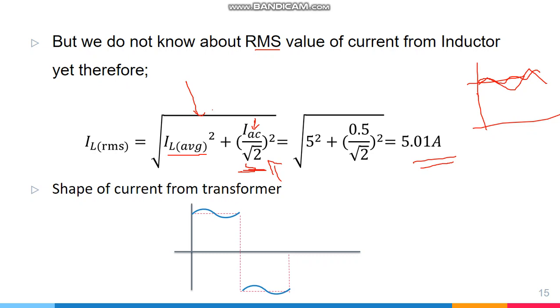You need to understand that this AC ripple is dependent upon the value of the second harmonic voltage V2H and 2 omega L. In our case the inductance was very high, 2.15 Henry, but in cases when this inductance is low, the ripple will be much higher.